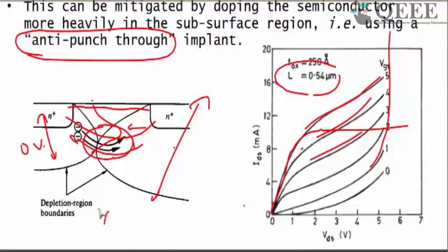One is that your VT is determined by your doping. If you want to reduce the VT, you cannot do that because you doped the substrate uniformly. The other thing is that your drive current depends on a quantity known as mobility. If your doping concentration is high, you can have a large number of scattering events with the impurity ions, so the mobility reduces. So you don't want a very high doping concentration at the surface. It's a real engineering problem, with a lot of trade-offs, so you have to carefully optimize your doping profile keeping all these things in mind.